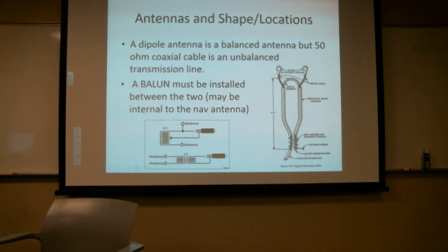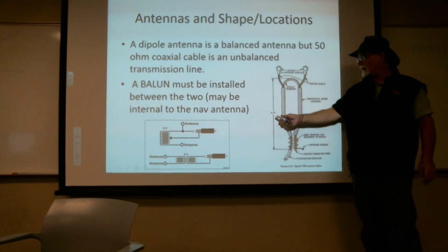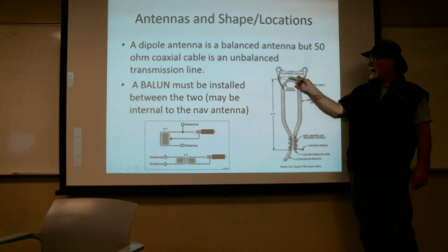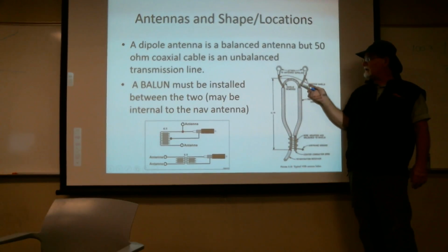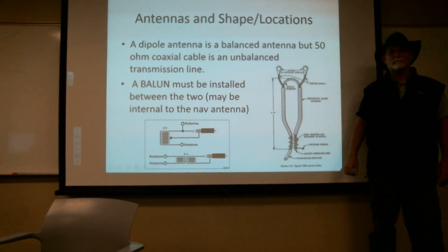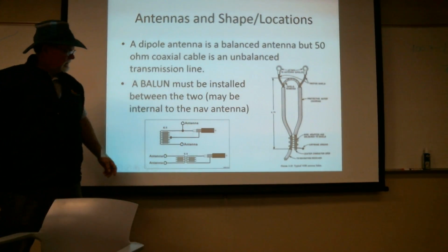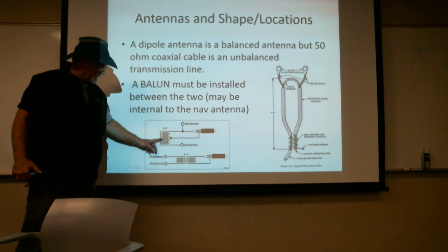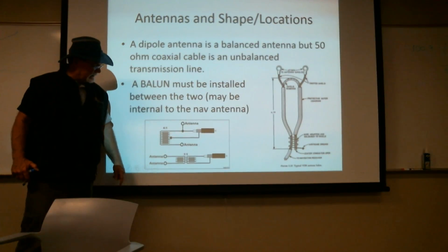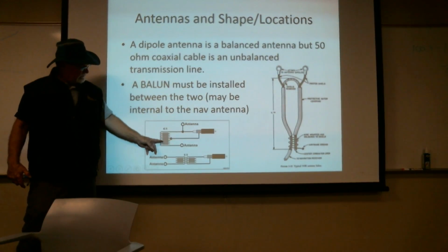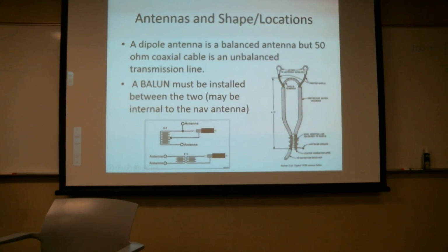There's actually several different wiring configurations for a balun, but notice what they're saying right here. Okay, 1/4 of the wavelength is going to be the length from there out to here. Okay, and then keep these guys relatively short. All right, so you may have to do something like that. There's another couple of different ways of coupling it. This is actually the same as that. This is a slightly different way of doing it.